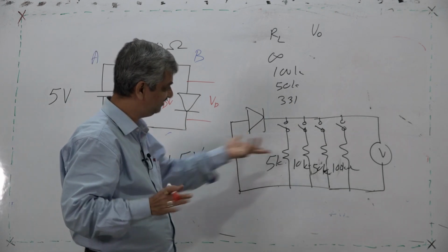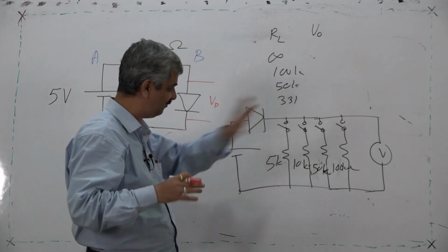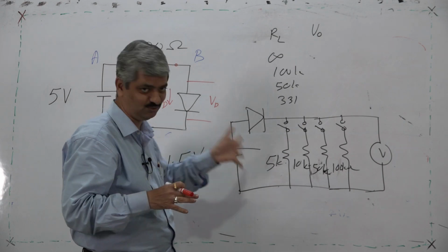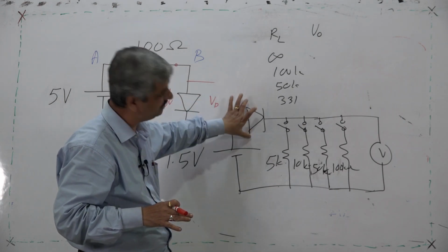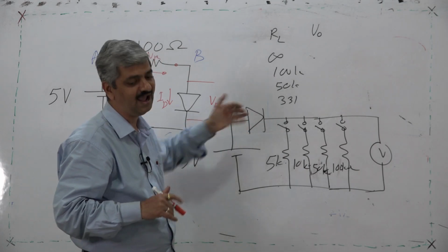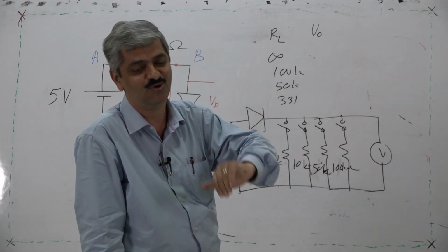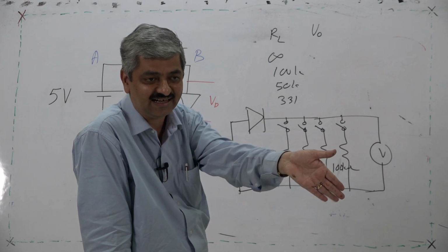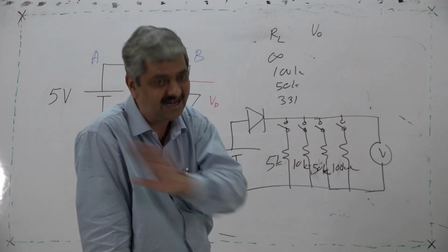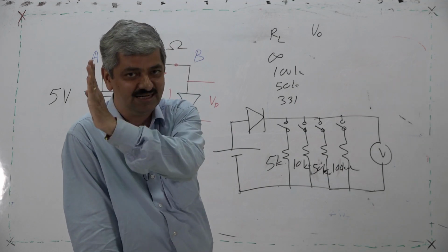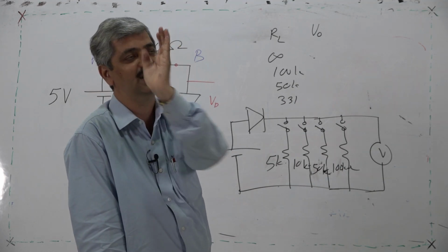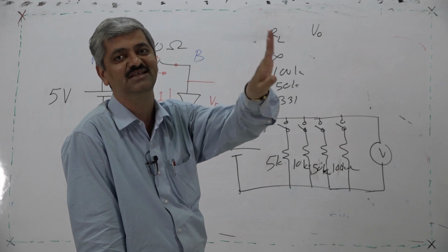Unfortunately, I do not know why such a kit is not designed. Using Proteus you can have it. So, when the resistance is there, sufficient current flows and 0.7 is eaten up by the diode. If sufficient current is not there, it cannot eat 0.7. So, the logic that you connect a diode on the left-hand side and at the output there will be 0.7 less is wrong.